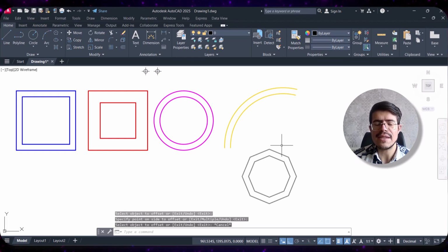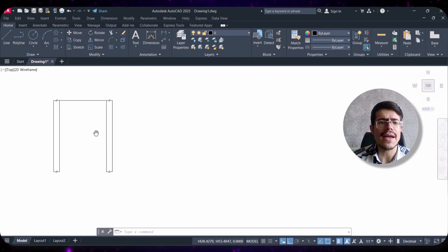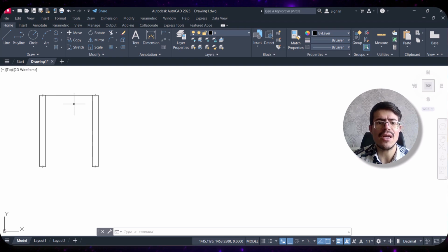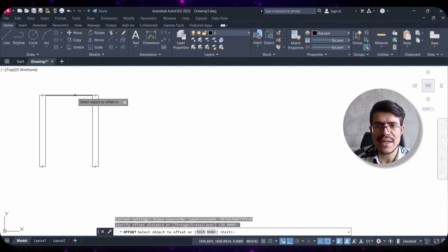After knowing these cases, as I told you, let's be familiar with some secret capabilities of the offset command. What are they? Let's go here. As you can see, imagine that I want to create stairs here. For doing that, if I use copy and do it one by one, it's time consuming. But I can use offset and give the value, for example 20, and I select this.